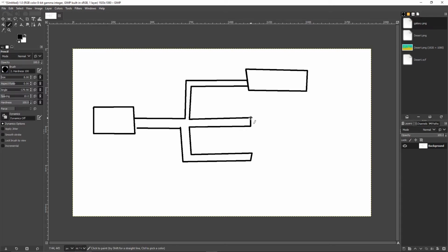Now, on your vehicle, you have a master cylinder. What does it do? Everybody has a master cylinder. What's it for? It's for the brakes, right? When you push the brake pedal down, it moves fluid in the master cylinder. The clutch system operates in the exact same way, and in fact, many modern vehicles use the same master cylinder to achieve both. Older vehicles, you would have a master cylinder for the brakes, a master cylinder for the clutch, and two different reservoirs for the brake fluid.